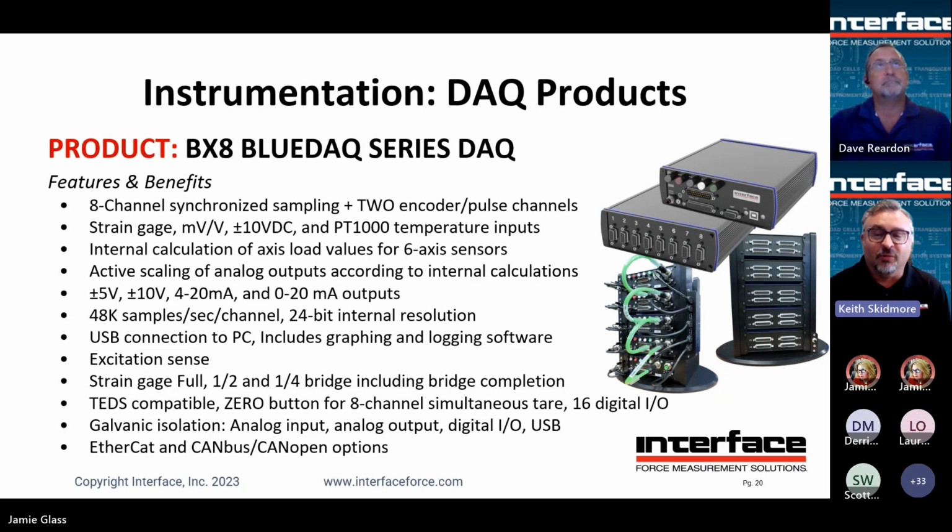Works with our Blue DAQ software. This is included, and the software is actually written in LabVIEW, so it's very LabVIEW compatible if anybody has their own LabVIEW requirements or software they want to connect to a BX8. Another thing, they can be combined and synchronized together. They sample 48,000 samples per second synchronously on all 8 channels. If you have 16 channels, you combine 2 of these, you have a sync cable that connects them together and syncs all the input channels together.